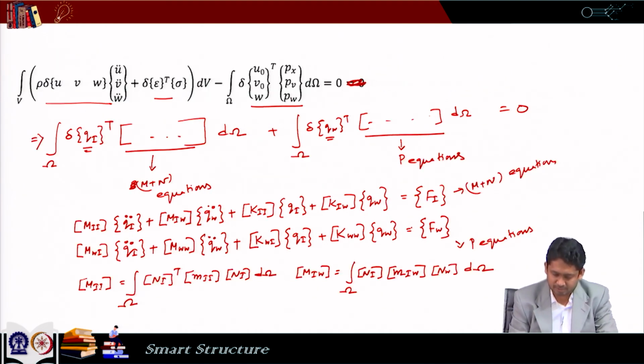So, here we can see that if the laminate is symmetric, then these two terms vanish, because in a symmetric laminate B matrix is 0 and this stiffness matrix and this stiffness matrix have B matrices. So, these two stiffness matrices do a stiffness coupling between the in plane components and the out of plane components.